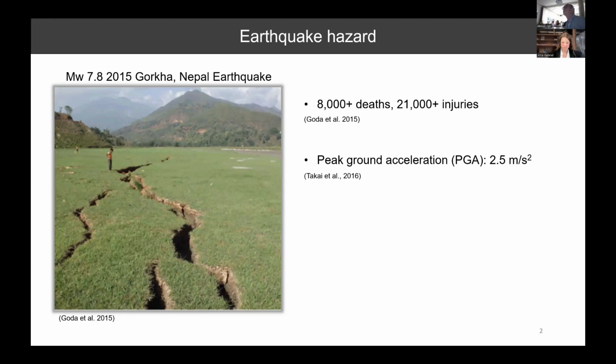Another relevant statistic is the frequency spectrum of the ground motions. It's widely used for building design because different architectures are sensitive to different frequency bands. What is interesting or unexpected in this earthquake is that, because of the local basin, we see unexpected low frequency ground motion. And this is what I'm also going to deal with in one of my chapters.